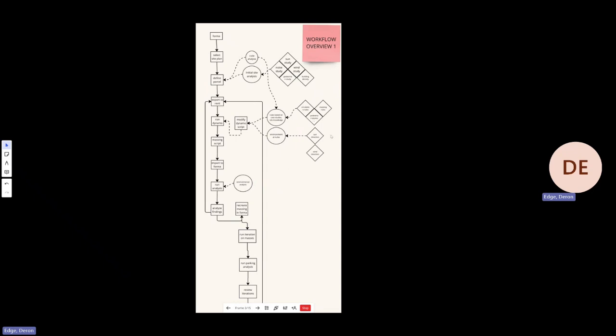Now, this first workflow is basically just an idea to iterate through the process, right? So for example, you would start with Forma, develop a site plan, and specify a parcel that you are going to define the site on. And whenever you know that parcel, you can start doing things like code analysis, or you can run initial site analysis, things like a wind study, building density studies, pedestrian flow studies, noise studies, things along those lines. And that all feeds back into the parcel.